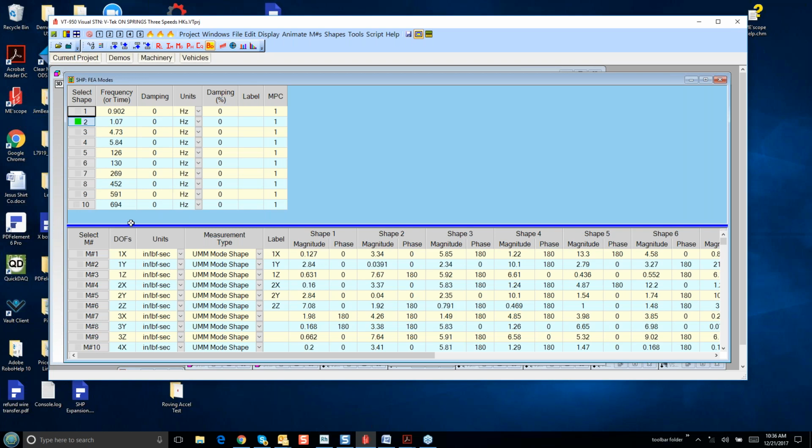We're simply going to take the shapes themselves and curve fit them to the experimental data, using the assumption that all the modes are excited at all frequencies. So we just looked at some data at 3 different speeds, 985 RPM, 1400 RPM, 2200 RPM, and we curve fit this data.